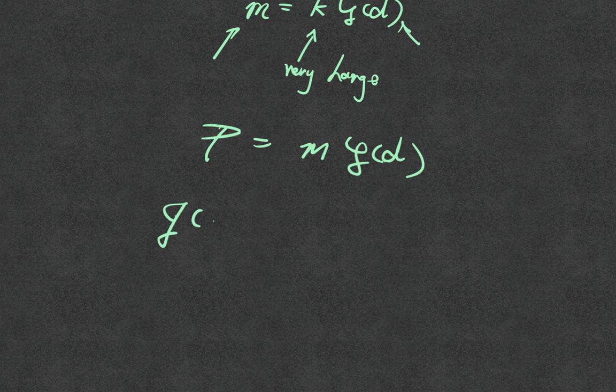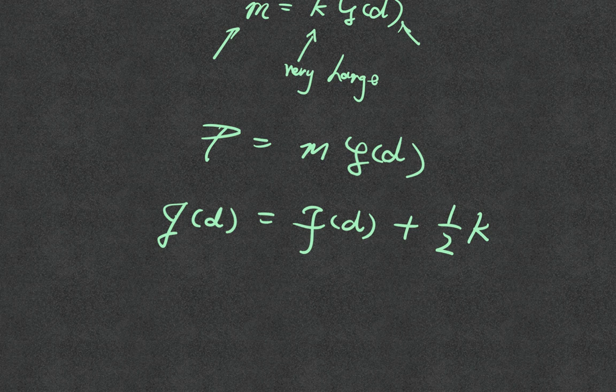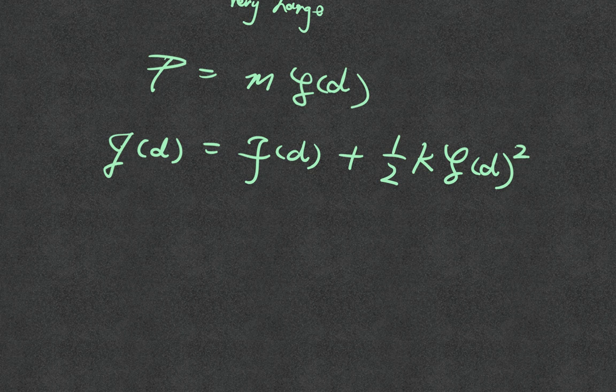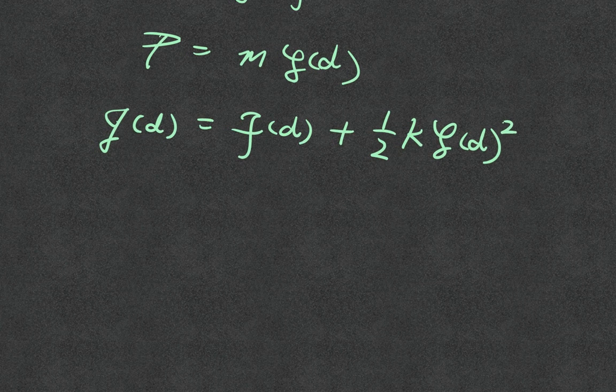So I will write this as the original elastic energy plus K times that penalty energy. I put a 1/2 there just to make it quadratic, but you can actually take out the 1/2. Do you know why? Because K is a parameter that you don't know exactly, you just know that it's very large. That penalty has a physical meaning, but you don't directly control it.